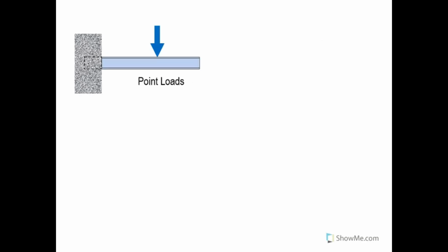Let's do exactly the same again, but this time we'll show a point load, and this is much easier. So this will be part way along the beam, and we'll draw it as a simple diagram with the point load, the value of P. So to calculate the moment, we know that the moment at the tip is 0 because there is no restraint.